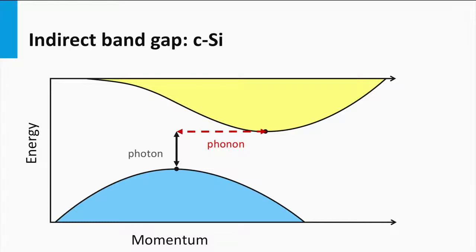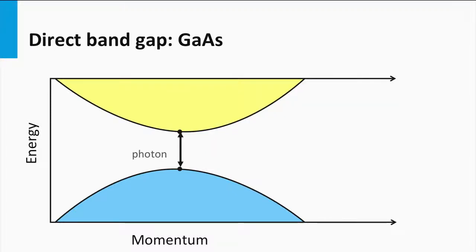If we ignore Shockley-Read-Hall recombination by defects, the radiative recombination in an indirect bandgap material like crystalline silicon is inefficient and recombination will be dominated by the Auger mechanism. For a direct bandgap material such as gallium arsenide, under moderate illumination conditions, radiative recombination will be the dominant loss mechanism of charge carriers. For very high illumination conditions, Auger recombination starts to play a role as well.